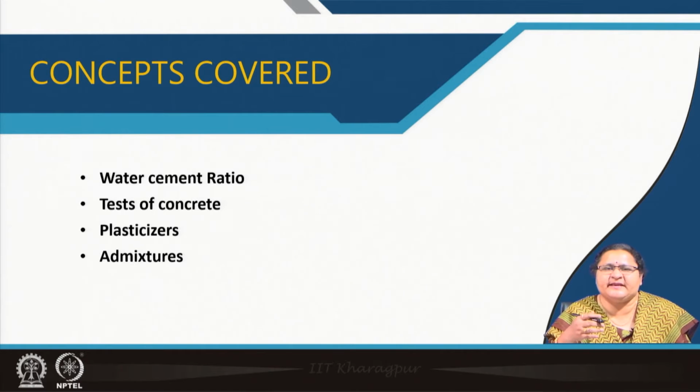So, if we mix more of water, the entire thing will pass very easily. But is it so easy? Cement will get enough of water to get hydrated. So, we can keep on adding water? No. So, we have to stick to a particular water cement ratio, and why we will come to that. And we will also see the tests of concrete, go to plasticizers and admixtures and finish this module.